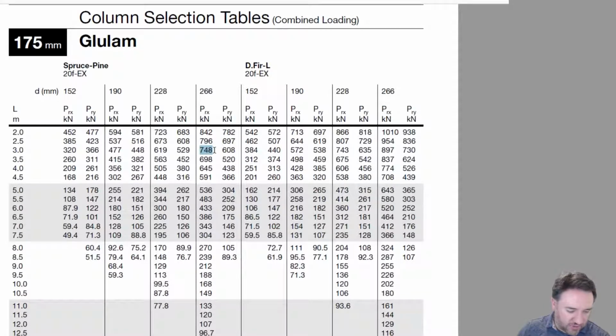And remember that our applied axial force was 488. So this is more than double. Or it's not quite double, it's less than double. But remember that we have a square on this term. So if we're using up half of the axial load capacity, only a quarter of it goes into our interaction equation because it's a half times a half. Okay, so these numbers are looking kind of okay. And this might be an okay section to choose. So I'm going to go with that.